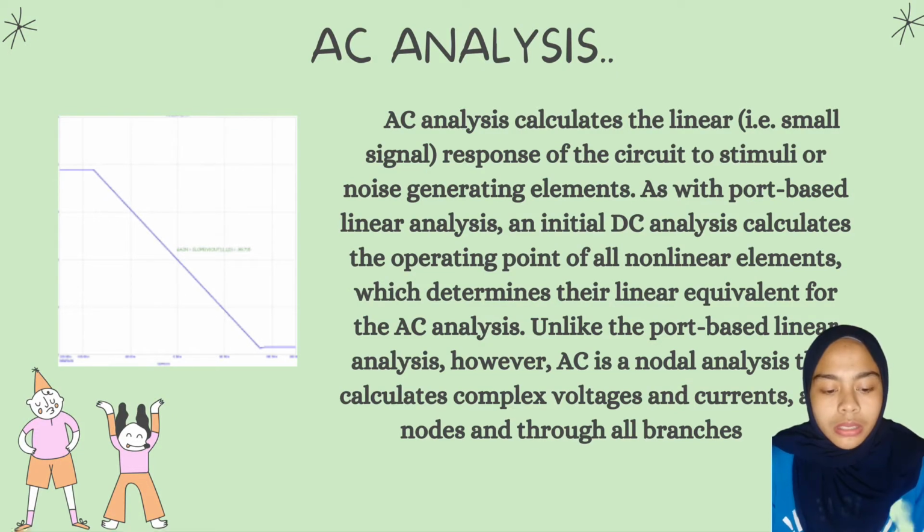AC analysis calculates the linear response of the circuit to stimuli or noise generating elements. As with both SPICE linear analysis and linear DC analysis, it calculates the operating point of all nonlinear elements, which determines their linear equivalent for the AC analysis.